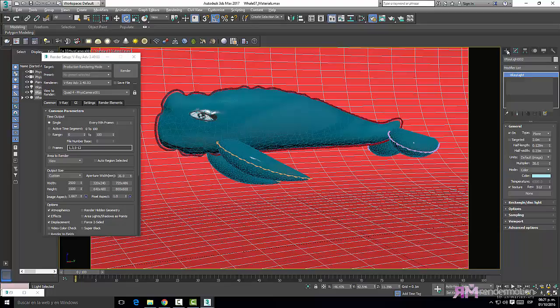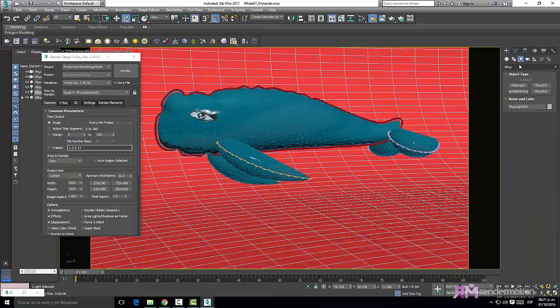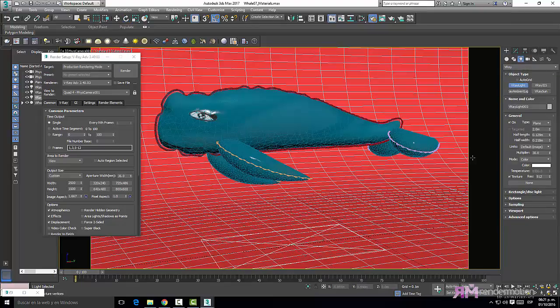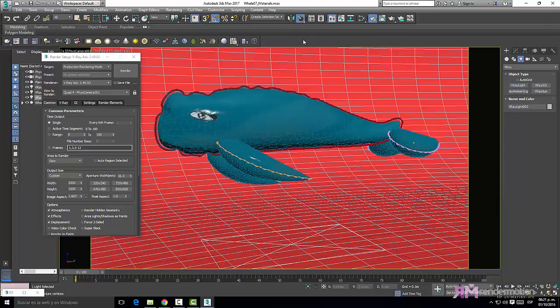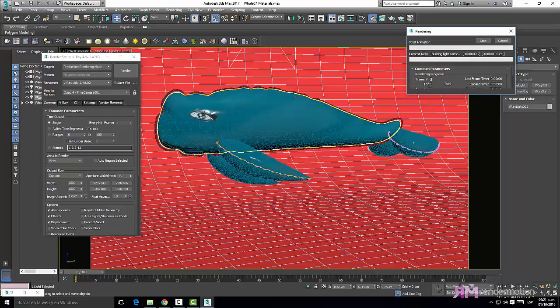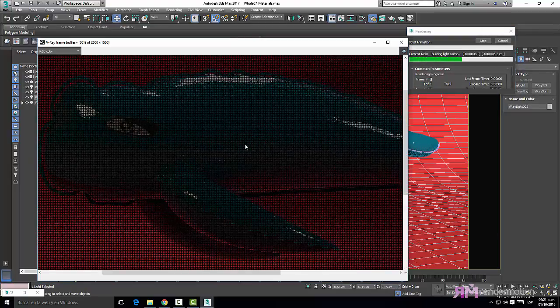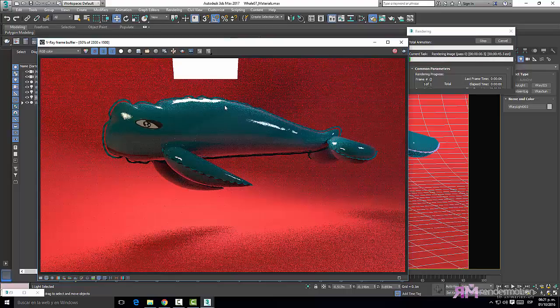I could create a light here. Look, I'm going to create a V-Ray light here, and I'm going to make it white. And here is a tool that's called Place Highlight. I think it's this one, Place Highlight. And selecting the light, I can click over the surface of the object. And I'm placing a highlight right there. Look, in the render you can see the highlight here. Okay, so now I can see the light also.